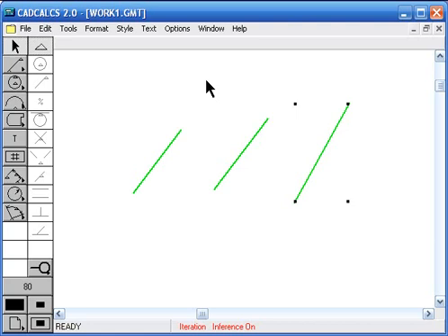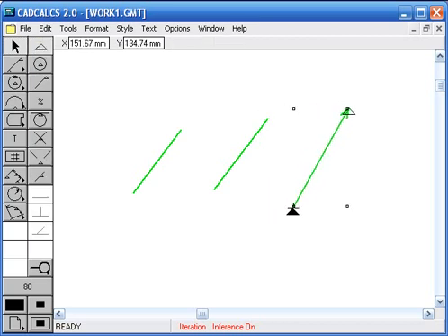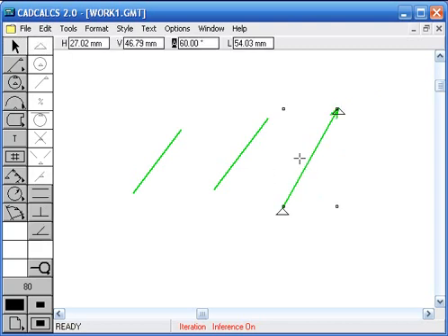This is a numerical constraint I allocated. So now this line has its start point here and the angle is constant. That is when I allocated the numerical constraint using the value bar, but I can also say that the length of this line, this is the length constraint, we will explain it later. I could give a length by entering the value directly, let's say 40 millimeters, or I can enter a formula.